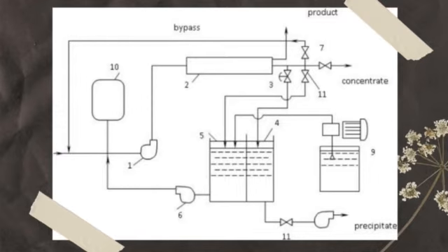A novel procedure is being developed to boost recovery value by using continuous crystallization of calcium carbonate at a constant supersaturation level provided by a continuous rise in retentate TDS while the RO is in circulation mode. Through the use of crystallization, we can extract calcium carbonate from RO concentrate.